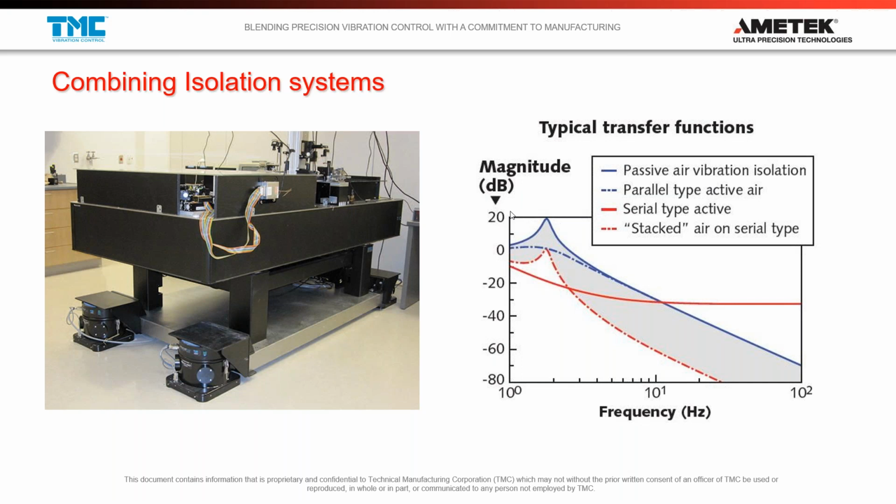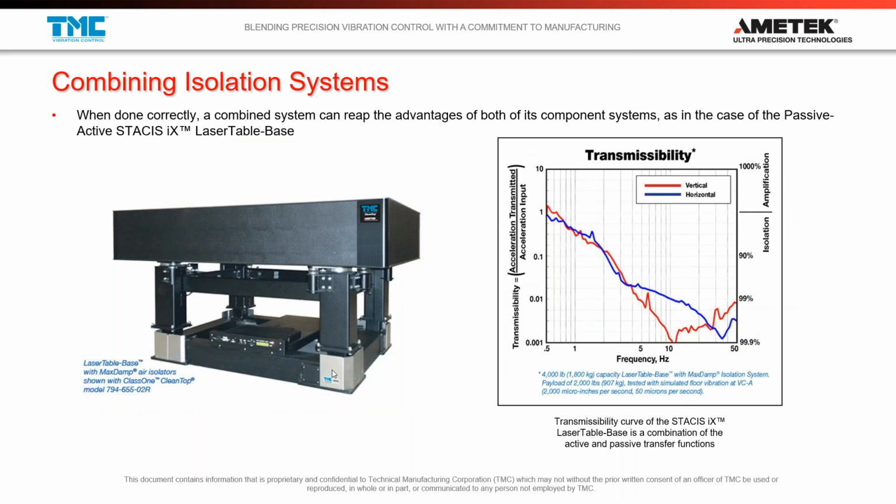What we did subsequently was we noticed we had this problem. We had this input of the air isolators kind of canceling out the good performance of our active systems underneath. And we developed a product called the laser table base, which really packages this all together, and it takes into account the fact that we have this resonance as part of a second stage of the system.